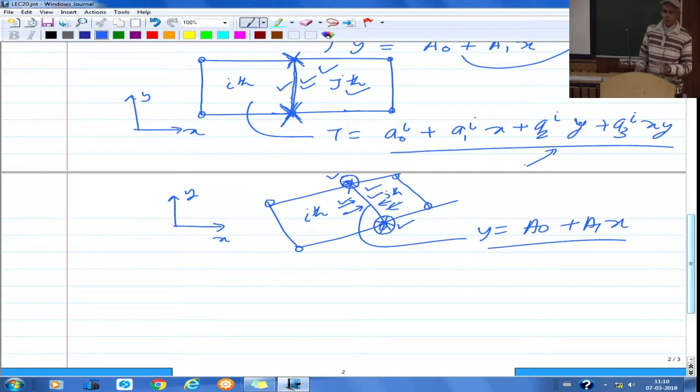No, it is not connected, but still you have a corresponding degree of freedom there. So, you have one additional term in the approximation. So, it is a better approximation compared to 8 noded element, although the performance would be marginally different in the convergence characteristics, but it is better than 8 noded because you have an additional term in the approximation within the element. So, the question was about the difference between 8 and 9 noded.